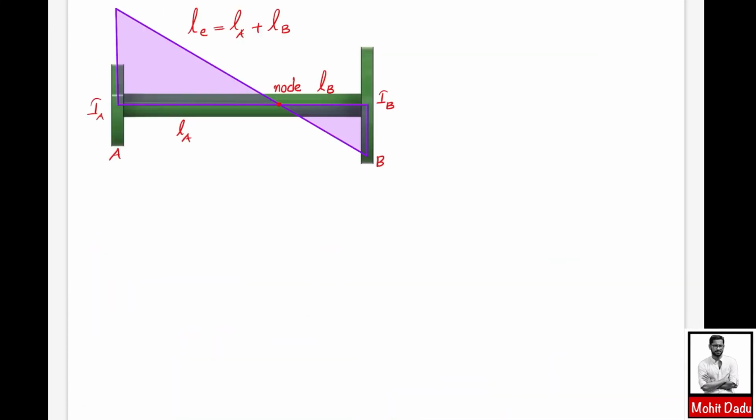So now we are having a single diameter shaft whose diameter DE, which is equal to D1, is equal to 100 mm, and you're having the equivalent length which is 1.0015 meter or 1,001.5 mm. So you know the concept of node. There will be a point where it is unaffected by the torsional vibration, and on one side it will be twisting in one direction and the other side in the opposite direction. And you can locate the node position with respect to the rotor.